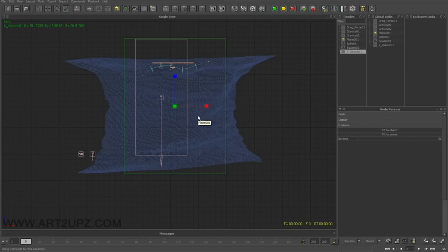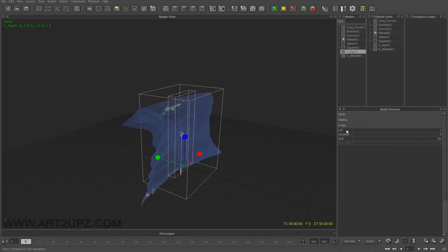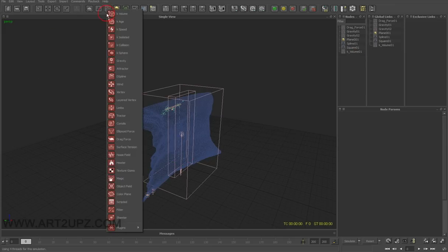Another kill option is by speed or by age. By age, when the life of my particle is, for example, one frame, all particles are deleted after one frame, but you can delete later and give variation. Or for example, you can set a speed limit, and below that speed the particle is killed. This is very nice for some situations.